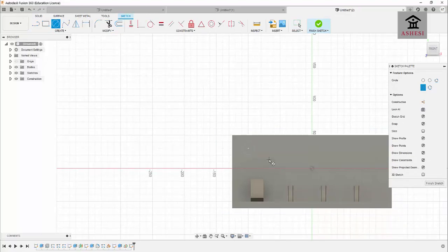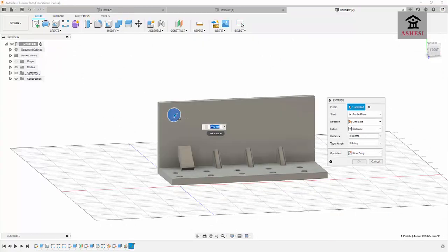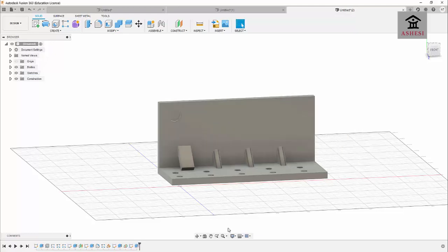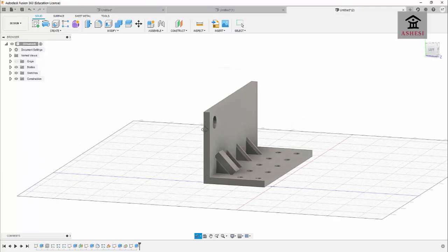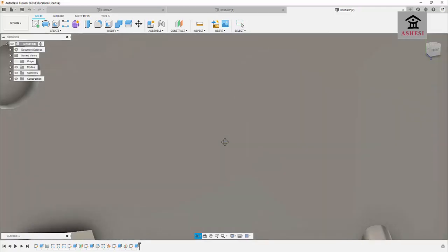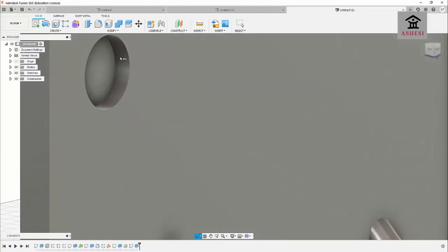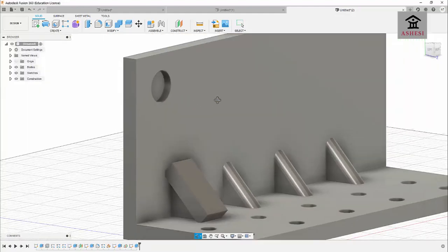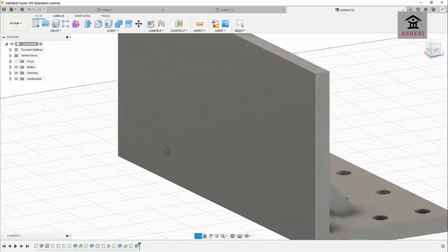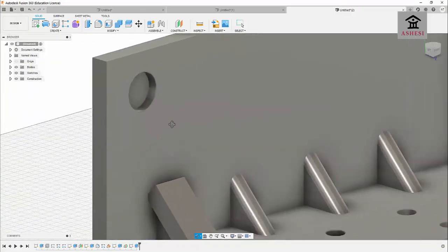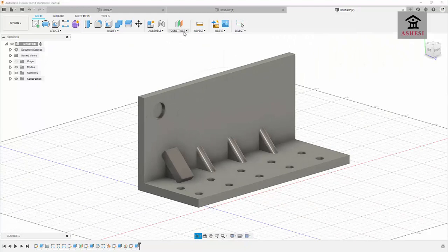and then I'll click on extrude. So let me make it 5 mm because I know my thing is 10 mm thick. So you can see that I have a hole that has been drilled here, but the hole is starting from the middle part of this feature and it hasn't gone to the other side of it. So this is one simple way of using the mid plane.